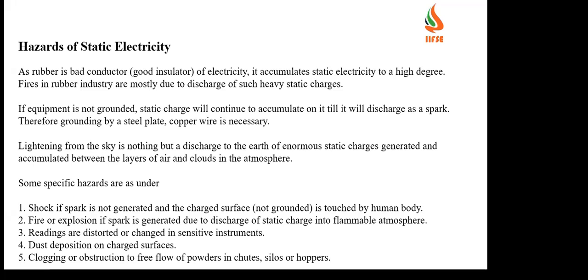If you see some of the specific hazards: shock, if the spark is not generated and a charged surface is touched by the human body. We can sense a small jerk or a small shock sensation. Fire or explosion, if a spark is generated due to the discharge of static charges into a flammable atmosphere. In case a flammable atmosphere is there, there is a chance of fire and explosion. If it is not a flammable atmosphere and discharge happens, we can feel a shock sensation.